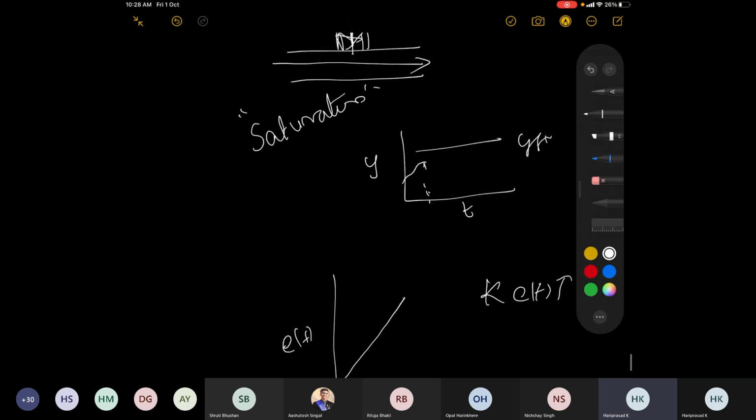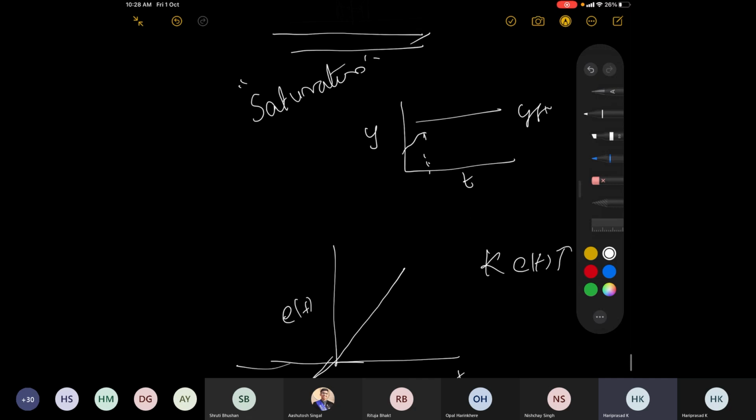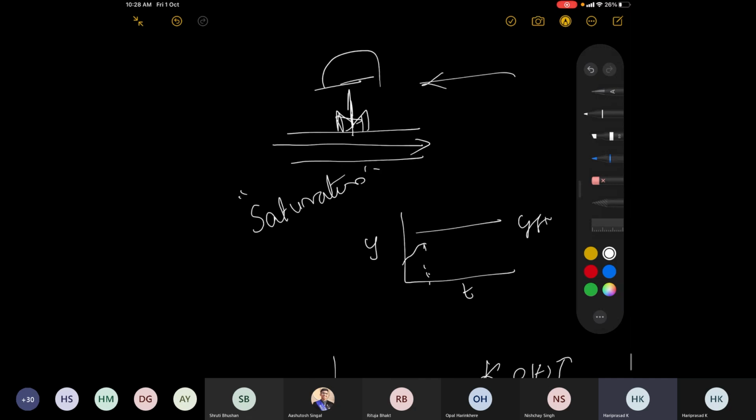Even if you try to push more and more, it would try to push the stem up. But there is a diaphragm. The diaphragm would say, this is what I can do. But again, it would start supplying air more and more. And this would unnecessarily create stress on the diaphragm, because you are always suggesting open, but it has done its job. You cannot do it anymore.